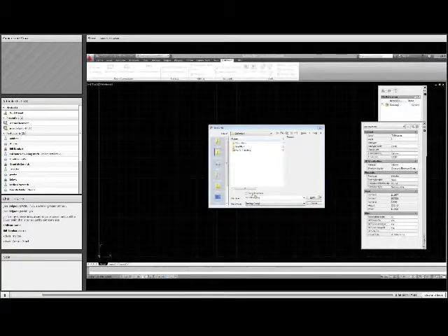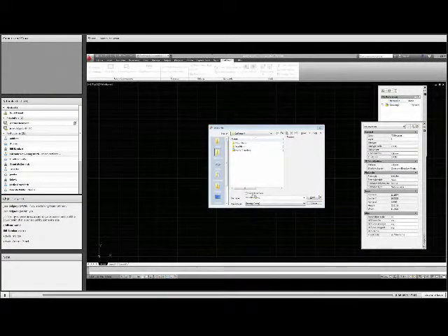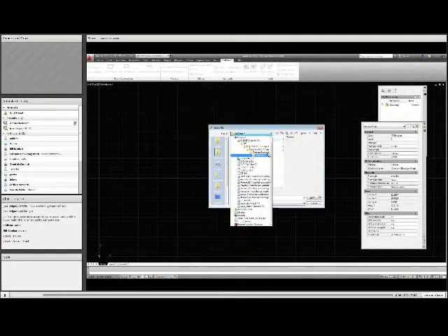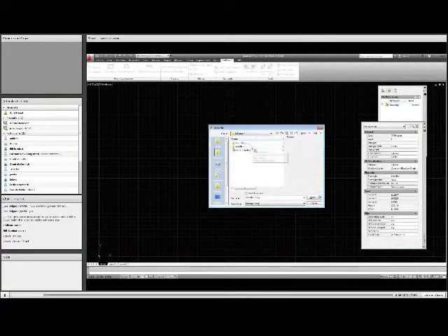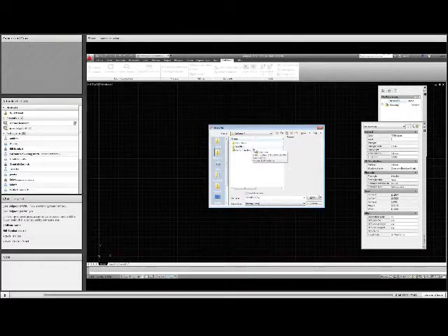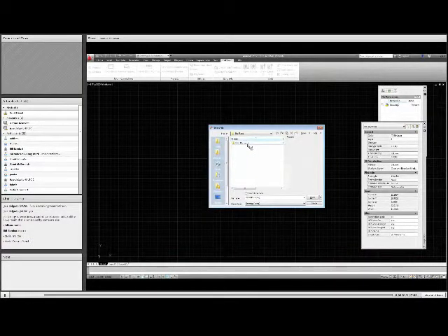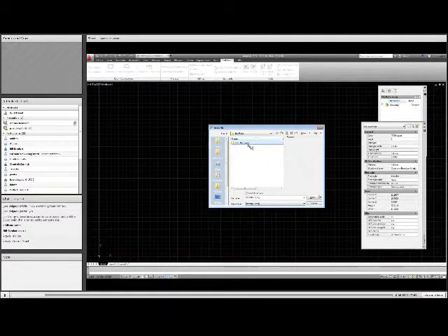All right. So as I said, I created a folder that is for the specific coordinate system, and inside that folder, I then break up the floor plans and the site plans. Each site plan has its own folder, and each building has its own folder. So going into the Esri Redlands site plan, what I had to do is export the GIS data into CAD, so I actually had CAD data to work with. It's a little backwards from what I normally do.